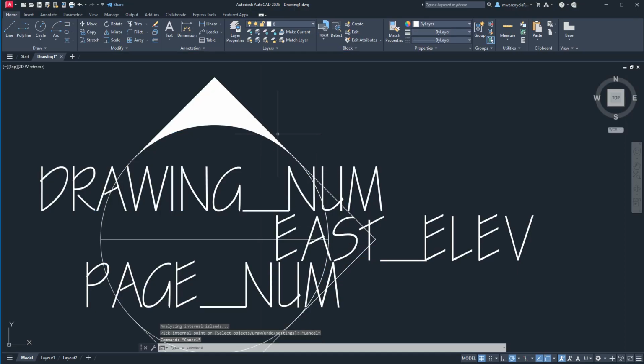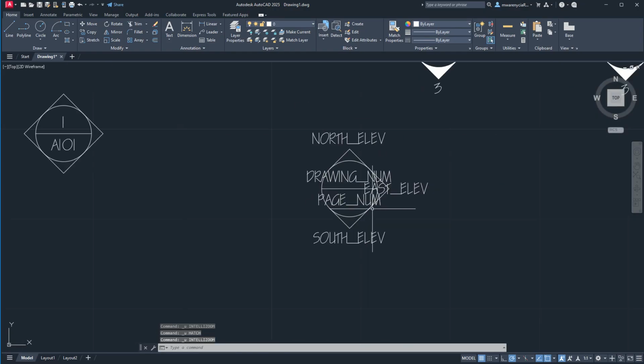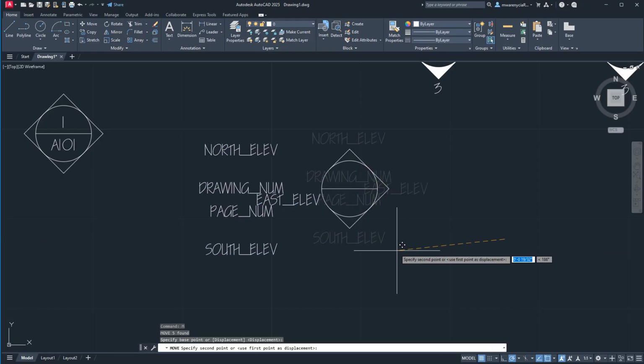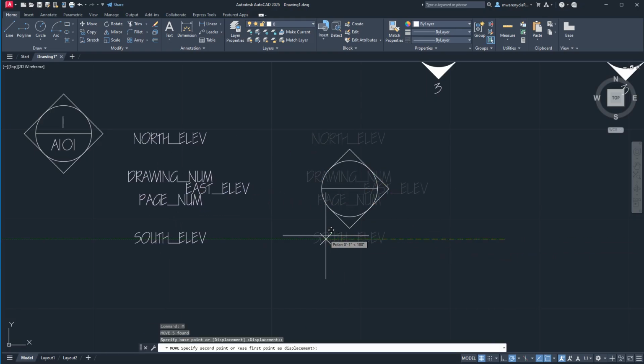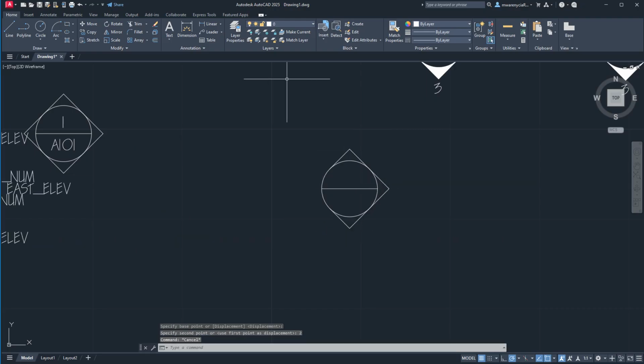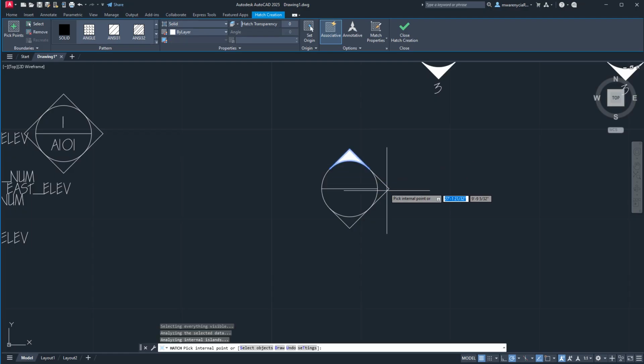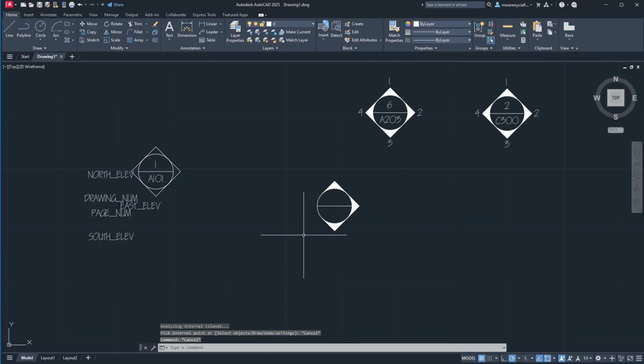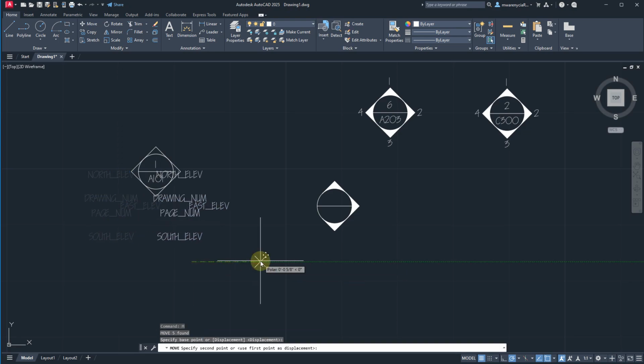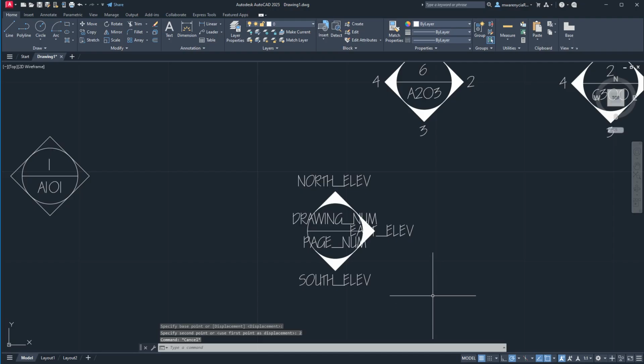Oh, right. It's going to be a pain because there's lines there. Let's go ahead and move. And this is a cool trick. If you move something a fixed distance, you can always just move it back the fixed distance. So I'll move this over 2 inches over there so it's completely out of the way. Do a hatch, fill, fill, fill. And then we'll move this 2 inches back so it's back right where it was.